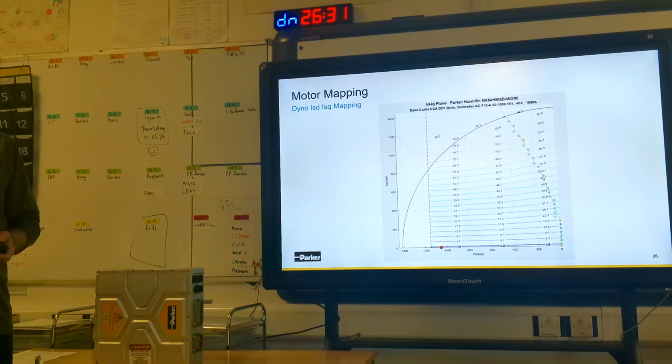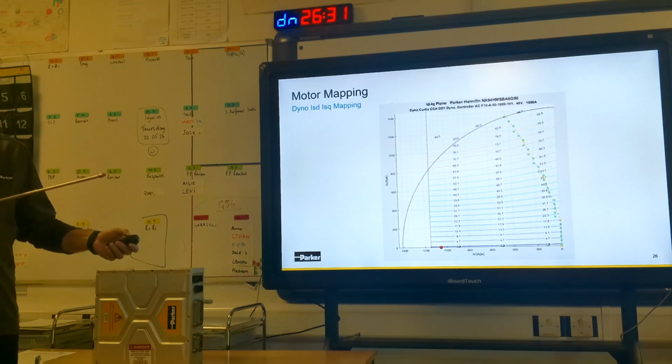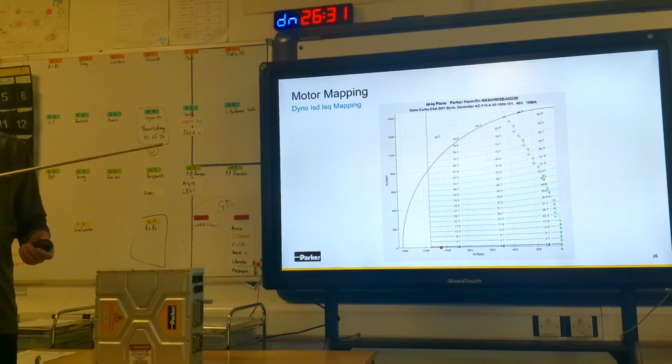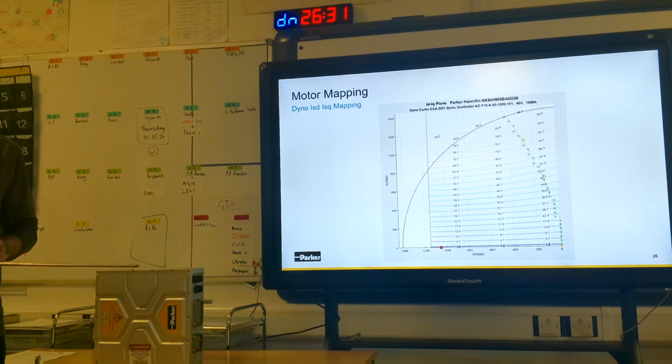So I've known people who end up with 3D lookup tables to take into account the temperature as well, because it turns out for traction applications, it's really, really important that if you say, I want 10 Newton meters, the thing produces 10 Newton meters within a reasonable accuracy. You don't want it to drift particularly. So traction applications, especially on vehicles, tend to be quite demanding, or can be. Depends on your vehicle.